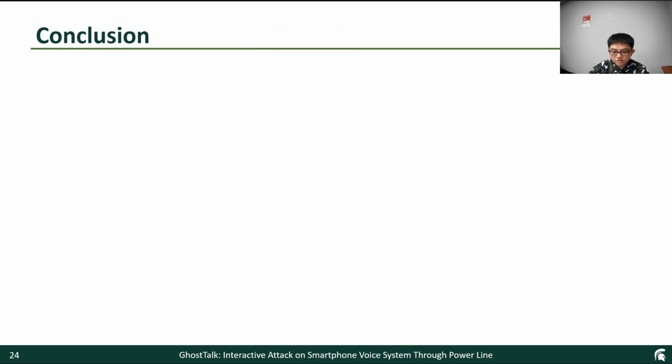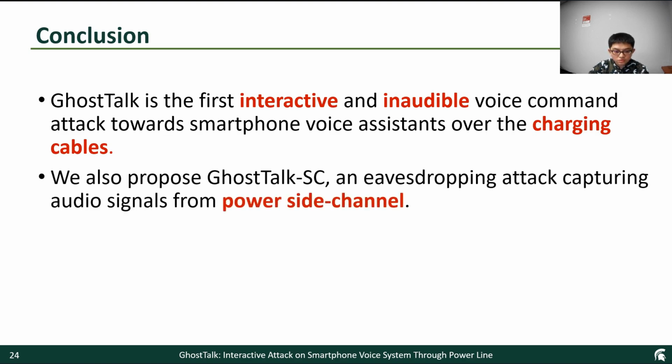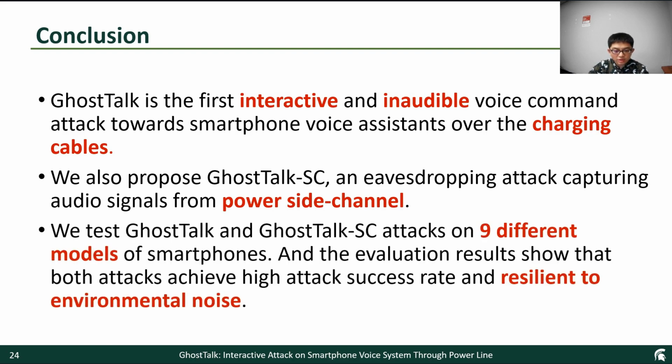Here is the conclusion. First, GhostTalk is the first interactive and inaudible voice command attack towards smartphone voice assistants over charging cables. Second, we also propose GhostTalk SC, an eavesdropping attack capturing audio signals from the power side channel. Finally, we test the GhostTalk and GhostTalk SC attacks on 9 different models of smartphones, and the evaluation results show that both attacks achieve a high success rate and are resilient to environmental noise.